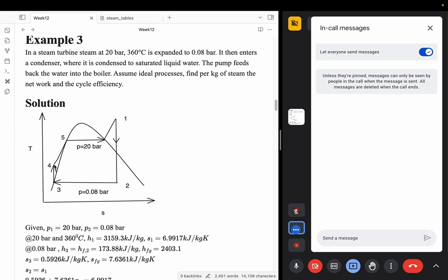That is also the same. That is also heat being added at constant pressure. So you are in the subcool stage, you add heat, and it will come to liquid state. Once it comes to liquid state, when you are adding heat, the temperature does not change. Like during the phase change, temperature remains constant, right? This is that portion where your temperature is constant. And once it becomes vapor, if you add further heat, the temperature will keep on increasing. So there comes another line.